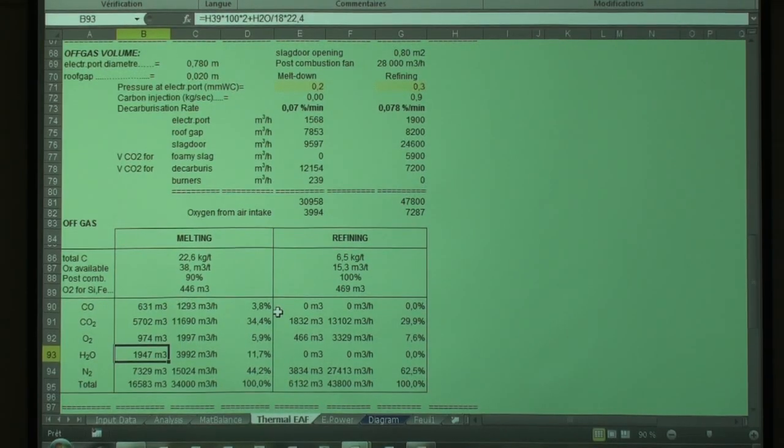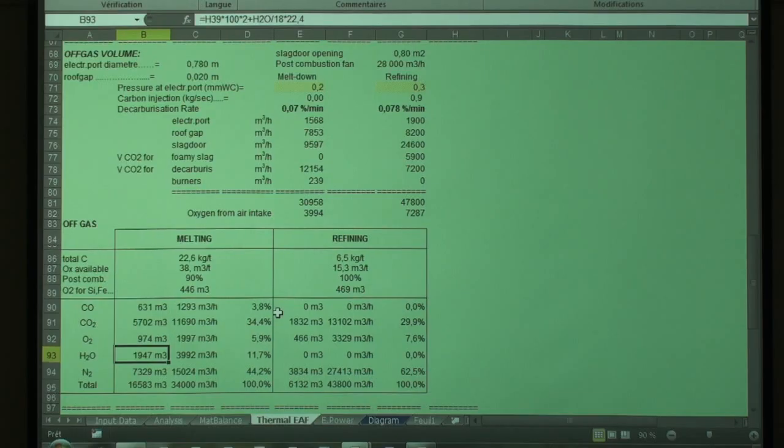Because at this high temperature, you have to create CO, otherwise you burn iron and you lose yield. And what people are selling is billet. That means they need iron to make the billet. And anyway, less oxygen means that we can increase carbon, and 1 kilogram of carbon costs less money than 1 kilogram of iron.